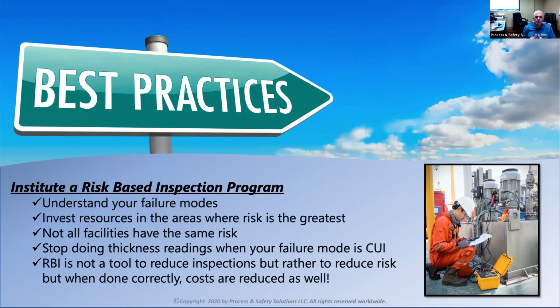RBI is not a tool to reduce inspections, but rather to reduce risk. But when done correctly, costs are reduced as well. We see this quite often when we develop good RBI programs for some of our clients. We see not only a cost reduction, but also risk reduction as a result. They're spending their time looking more frequently at areas of higher risk, and less frequency and time is spent on those with less risk associated with them.